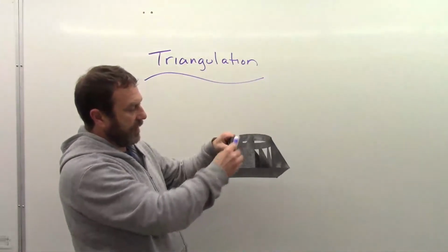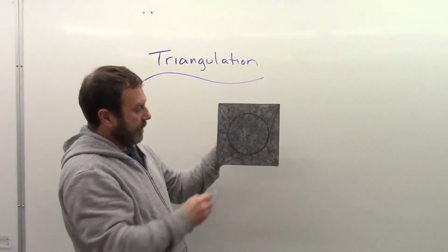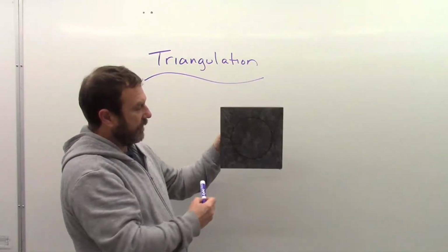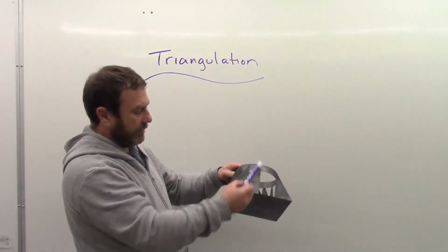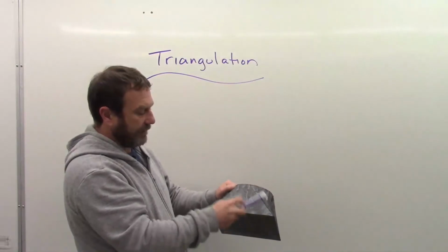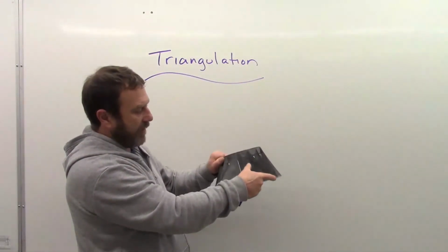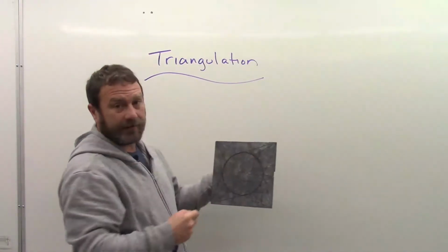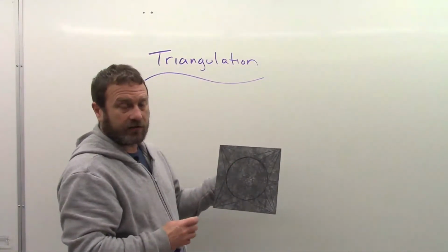So these would be the hypotenuse again that we'd be seeing from the plan view. But when we look at these lines in the plan view, they're much shorter than they appear to be here. The actual true length of that line, taking that distance, will not transfer to the same here. These are not true length. The element lines in the plan view are not true length.